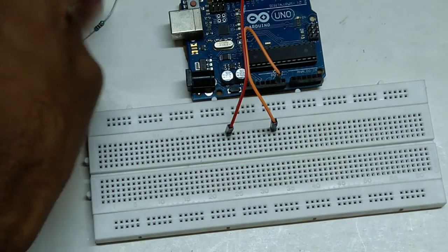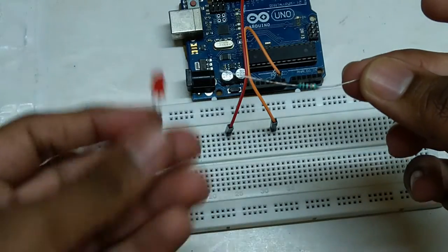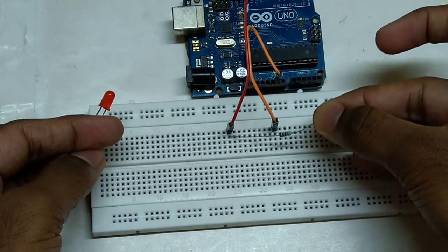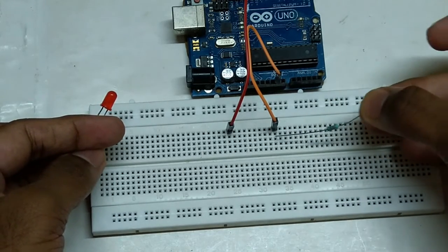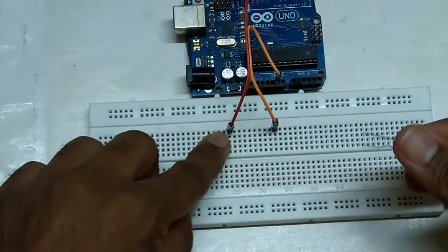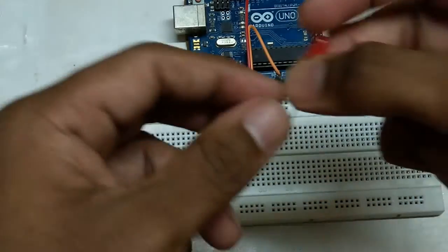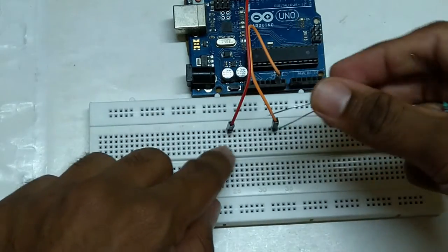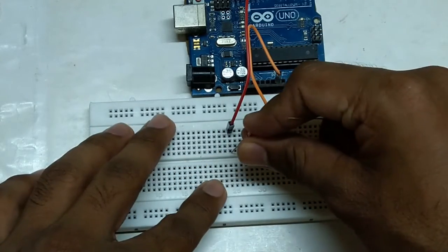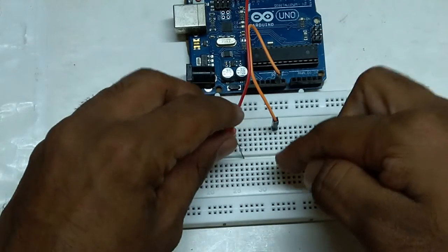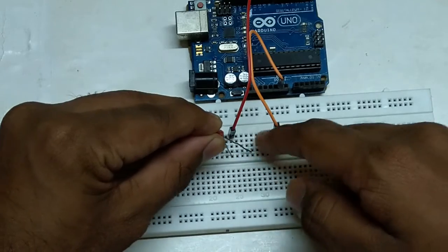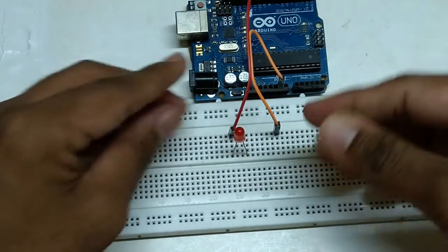So now we need to connect a resistor and an LED across these 2 points. So we know that the entire column is 1 point, that means all are shorted, and this entire column is 1 point, that is all are shorted. So this is from pin number 12. That means the positive end of the LED should go to pin number 12. So connect the longer lead right here, and then connect the negative one to 4 places after that, maybe like this.